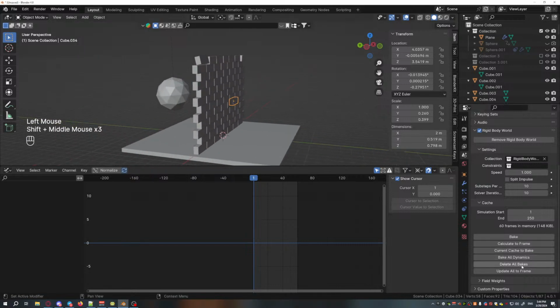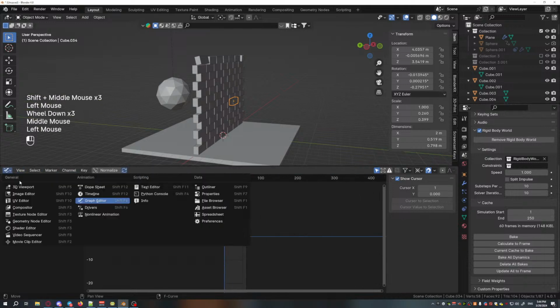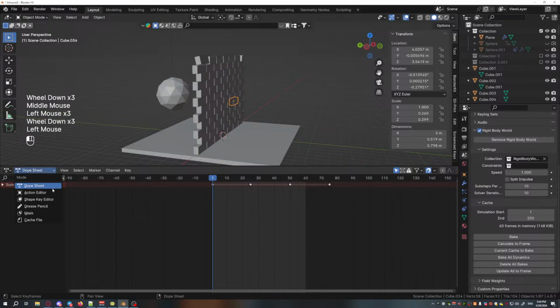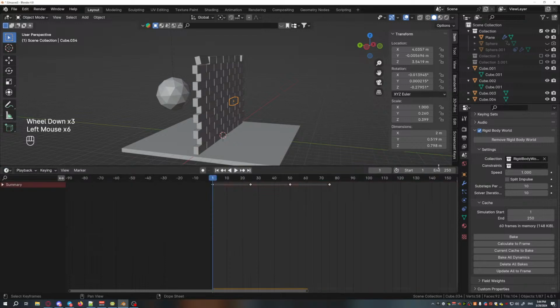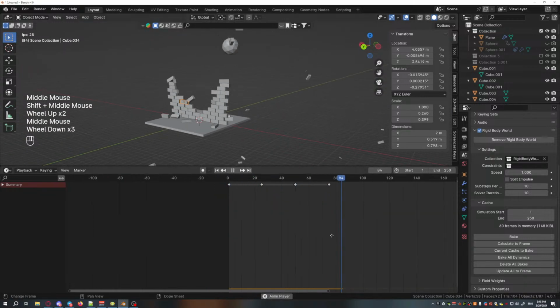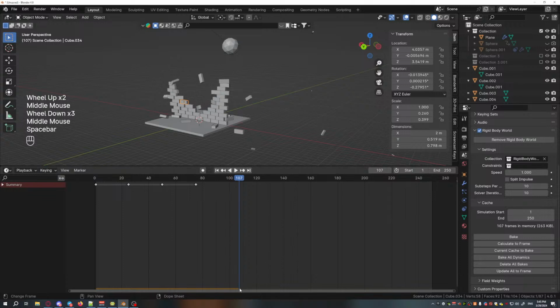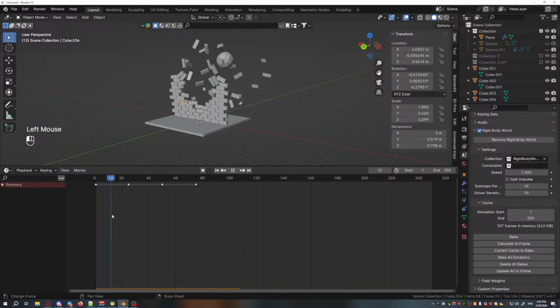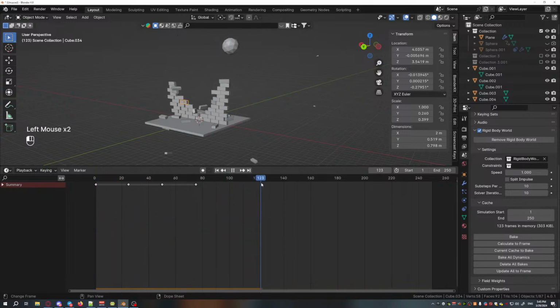And it runs the first time you make something, you animate something. And so let's, for now, delete all bakes. And let's, in our timeline, set the end of animation a little bit further to see how bricks are falling. And you can see down there a little brown progress bar. The bright brown is already cached and baked physics. Everything that is black,